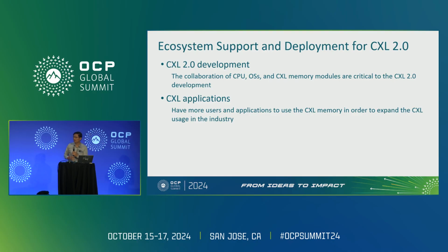There's something I don't understand. You're saying that you support memory sharing, but my understanding is CXL 2.0 does not support memory sharing. Yeah, good question. In fact, memory sharing in 3.1 uses MLD devices to do the sharing, in the standard Linux and standard spec. What we do is a proprietary way of mapping the device to two different hosts at the same time. We don't really lock the data. We just map the device to the two hosts. So the testing that I just showed is two CPUs reading at the same time.